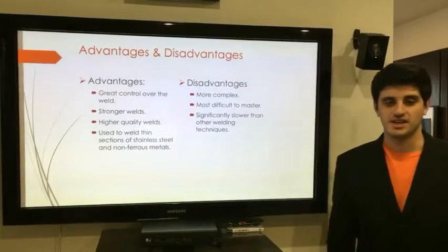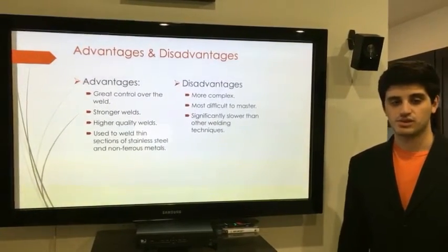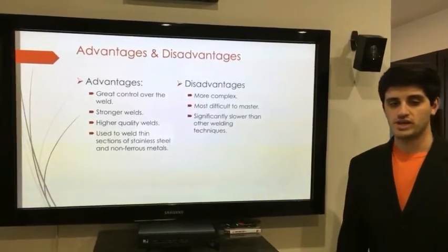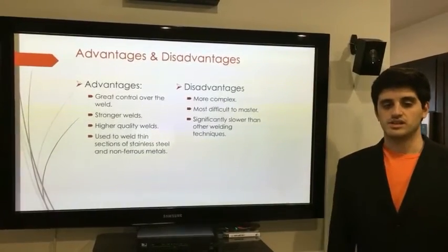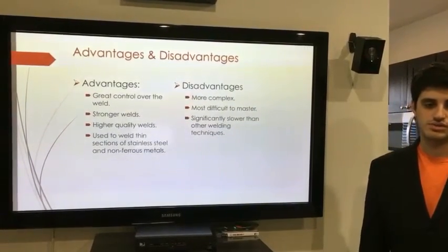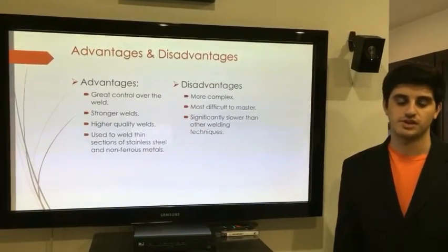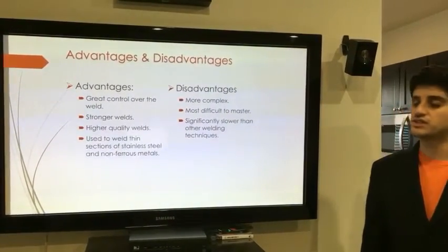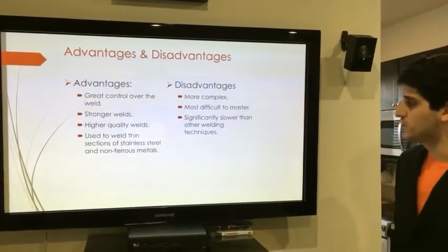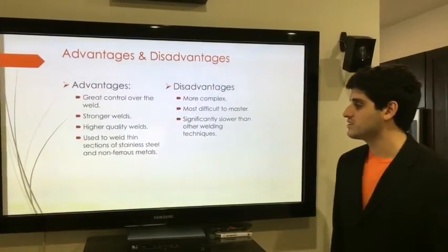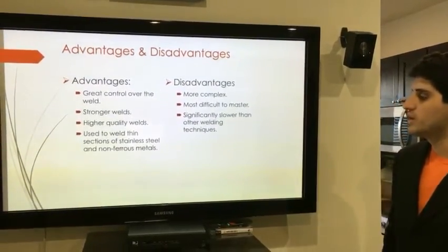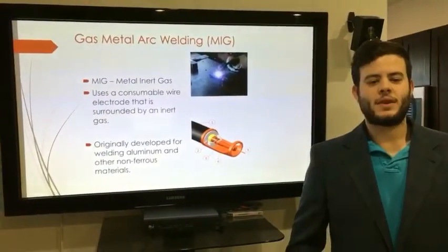Advantages and disadvantages. The advantages are great control over the weld, stronger welds, and high quality welds. It's also used on thin sections of stainless steel and non-ferrous materials. The disadvantages are that it's more complex, is the most difficult to master, and is significantly slower than other welding techniques.